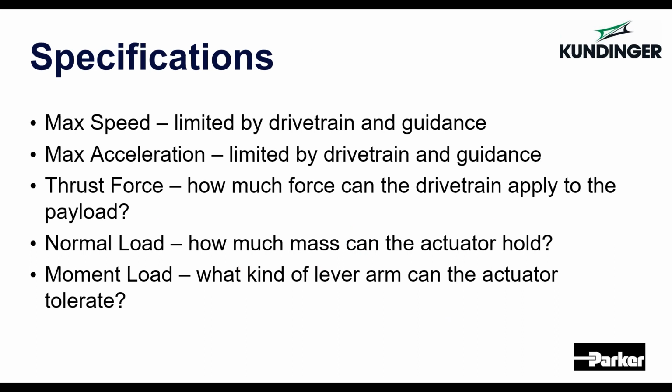Normal load. You'll see normal load specs in everyone's catalogs. I always say these numbers are really for nothing else than bragging. There's a lot of specsmanship that goes into these kind of numbers. You might see an actuator that you can put 2-3 tons of mass on, but you're not able to actually put any kind of offset loads on it, and your thrust forces on the actuator mean that you're only able to accelerate that thing at a fraction of a G.